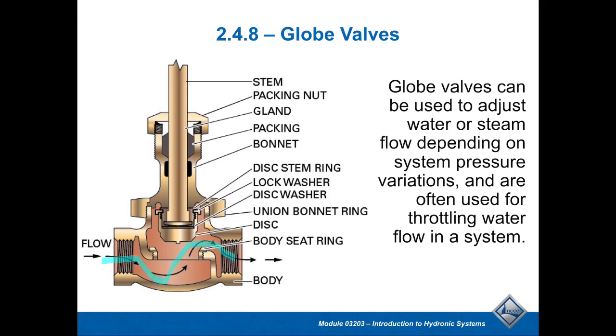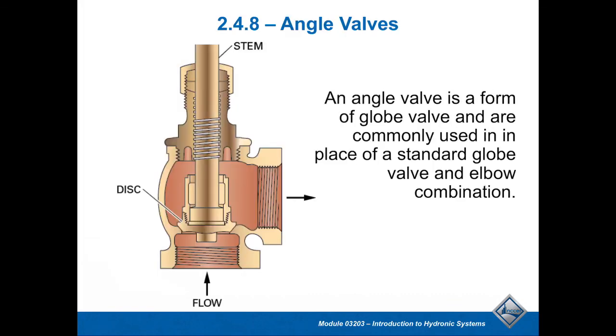So this valve is set up almost like a Z arrangement where the flow moves into here, has to make a connection, go back up, and then essentially make its way out. So this little disc that we're showing you here has to move up out of the way to allow the water, either more or less water, to flow into that system. So very nice little setup on those.